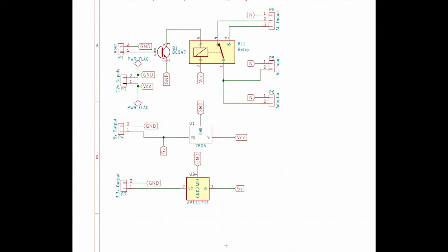So now let's look at the circuit diagram that is actually implemented in the board. We have a 12-volt supply where my mouse is right now, which is the 2 pins, the lowest pins to which we had connected our adapters. We're calling the positive 12 volts as VCC, and we're calling the ground GND. We had the input pin. The positive of the input pin is connected to the base of the BC547 transistor. All the flags that you see as GND are interconnected. They're all the common ground.